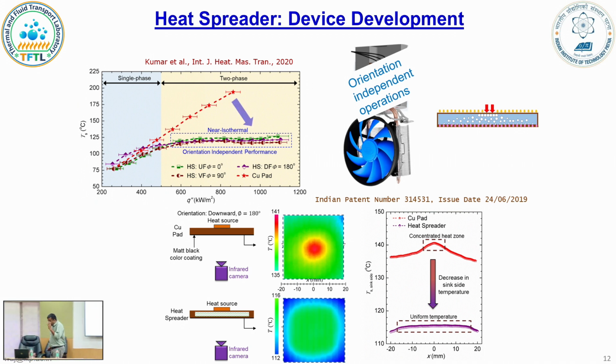So again, doing a calculation of how much the thermal conductivity is is slightly tricky here, because you can still not imagine or allow in your models isotropic thermal conductivity. So I would not like to comment on that. But if you look at the numbers, they really tell you that if 400 watts per meter Kelvin, or 384 watts per meter Kelvin, is the thermal conductivity of copper, what is the thermal conductivity of this device? So this is great. Not only is this great in terms of temperature, how much drop it can give you.